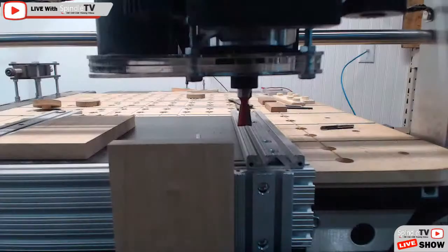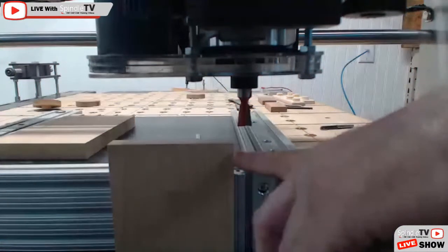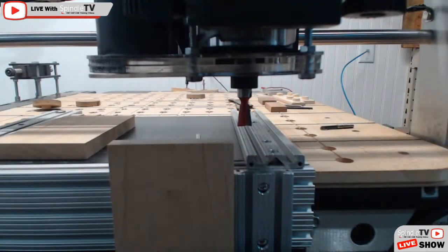Did you center the bit, or do you go to the corner start? You always start from the bottom left corner with the joint maker jig. You don't start from the center. You start from the bottom left corner. So my machine is zeroed out on the outside front corner. And let me switch cameras here. My machine is zeroed out on the outside front corner here.